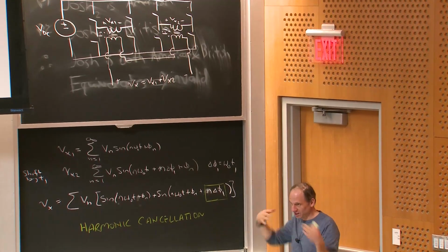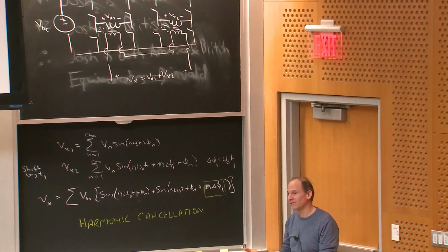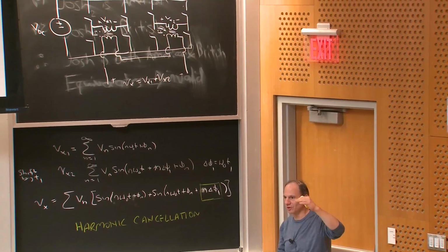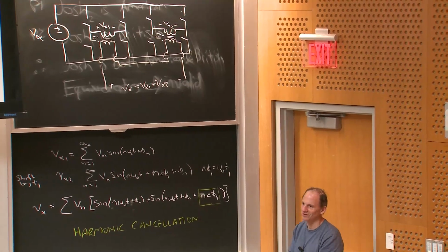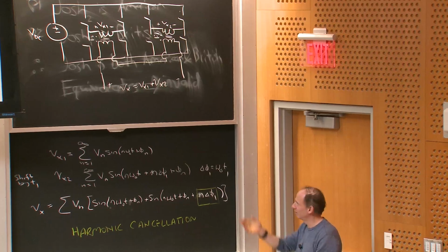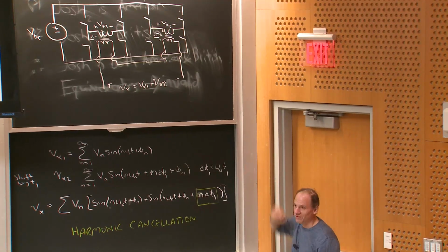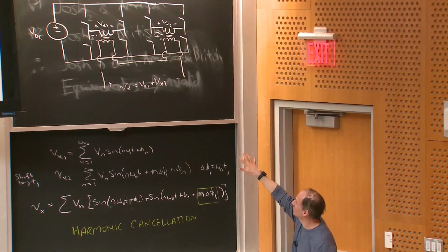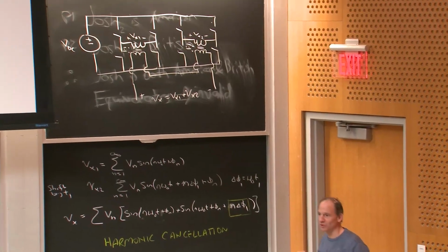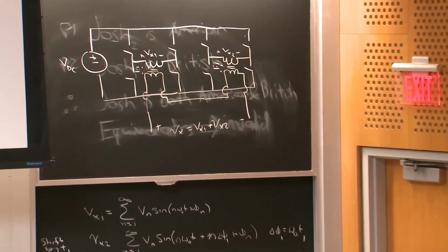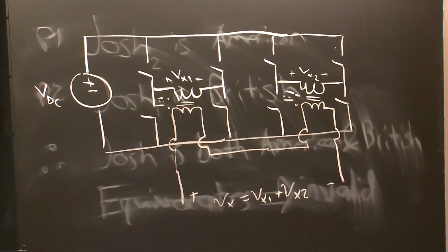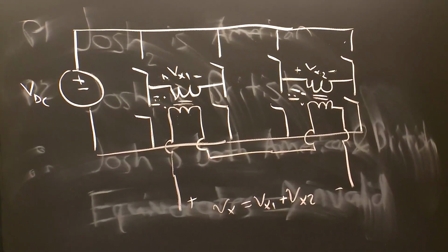We will see next class other circuits whose benefit is that, for a given input voltage, they use lower voltage switches to get the same output. So there's a lot of ways you can take advantage of the complexity you inherit. The downside to this one is principally that I have transformers that are rated for the frequency I'm outputting. In some cases I might not like that, but there are other circuits that get around that.